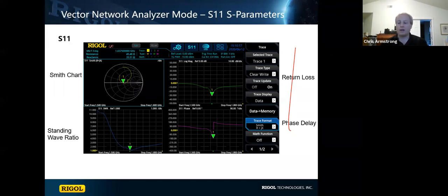For those of you who don't use them a lot, what a vector network analyzer allows you to do is look at frequency, power, and phase, or change as a modulation of that phase. And there's a lot of interesting data to be built up from, or diagnostics to be done from, how these complex RF circuits are altering that phase and what it means.